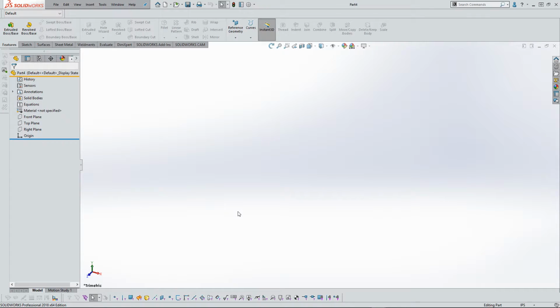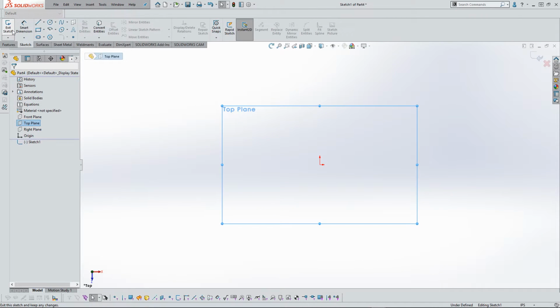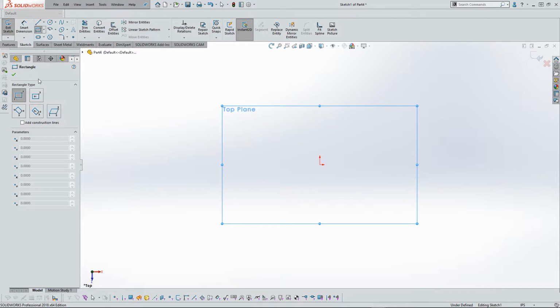It's kind of the same process, but it's actually a quicker route, and I'm going to be using a solid body, and I'm going to do just a standard extruded boss base on it. Starting off, I'm going to come into my front plane, or sorry, my top plane, and do an extruded boss base. And from here, the whole premise of why I do those reference planes, how I was saying, was I like to keep my origin in the dead center of my part, about 95% of the time.